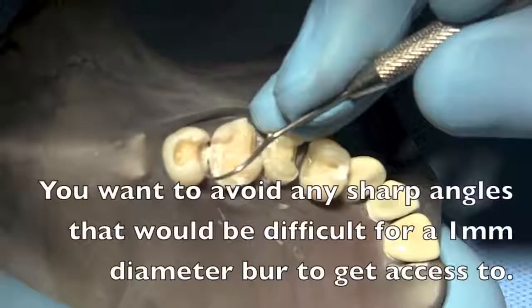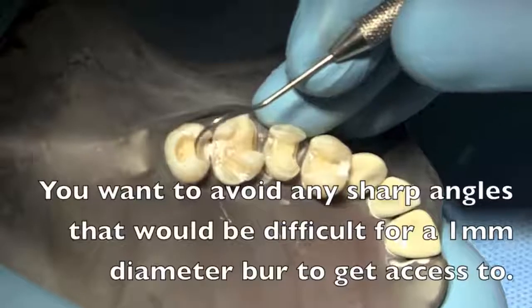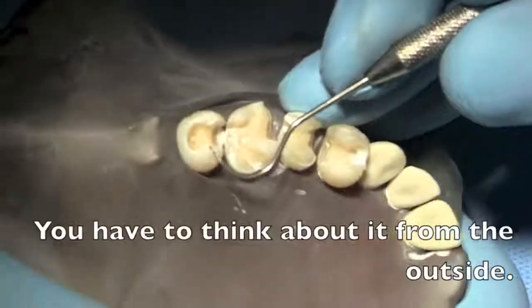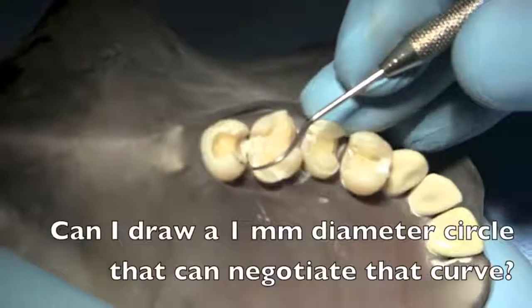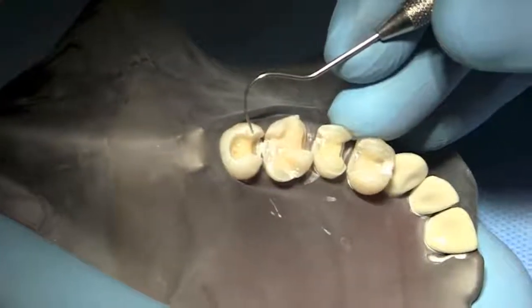You just want to avoid any sharp angles that would be difficult for a 1 millimeter diameter burr to get access to. So you have to think about it from the outside. Can I draw a little circle right here that's 1 millimeter diameter that can negotiate that curve? I sure can. Can I do it over here? These are the areas you have to watch out for.